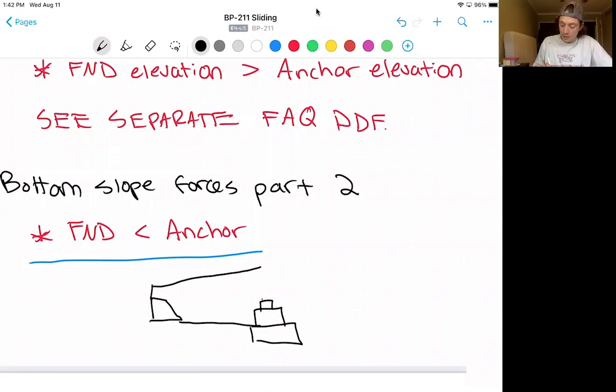Obviously not to scale, but we'll keep a horizontal bottom of the ramp wall here in order to make sure that the ramp walls aren't pulling down on that anchor. And because of that, we'll just discount the part of the tiers, aka in this case the foundation. We won't count that weight for resisting sliding because we don't want to rely on this connection right here.